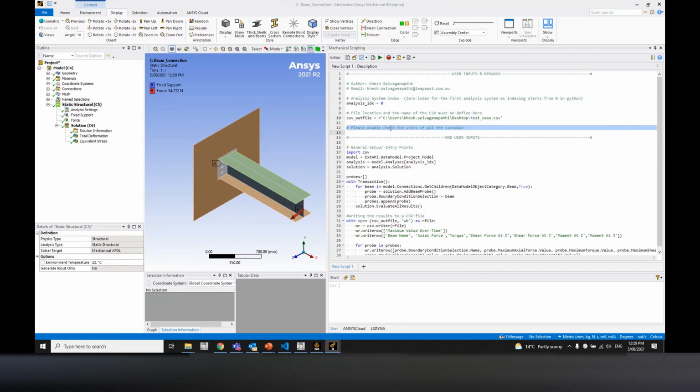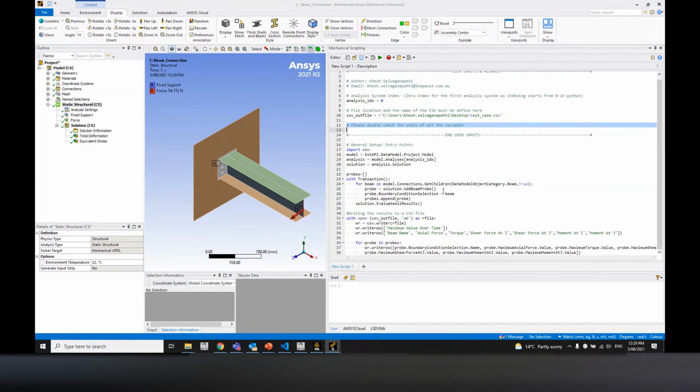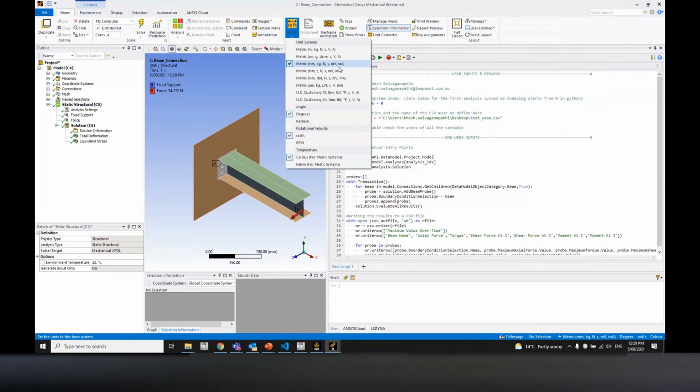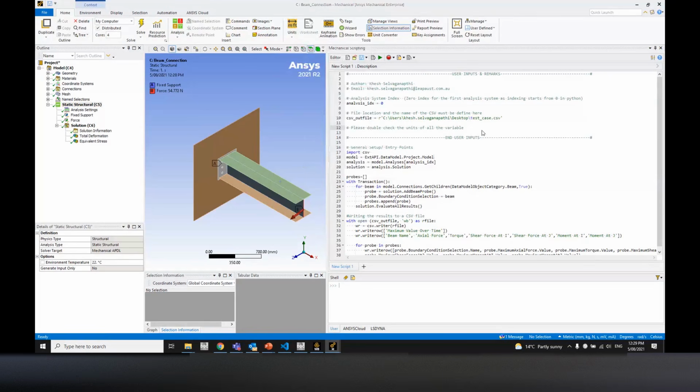Okay. We can get into units, but I don't recommend it. I don't write units in my CSV file at all. The reason being is the solver is in a consistent unit with whatever you're solving. But I want the users to check the units, because if I write a unit, force for instance, it's going to give me the pure unit, which is F is equal to MA.